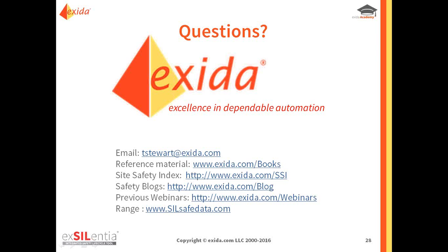All right, so how to find or validate failure data from products that are not SIL certified. Exida does a lot of FMEDAs for valve manufacturers to predict the failure rates. So what they're asking is, if there's a product that's not SIL certified, what do we do? Well, we do a lot of FMEDAs, and a lot of them don't have to get certified. They want to know what their range is. So if a certification is not in the picture, one does an FMEDA.